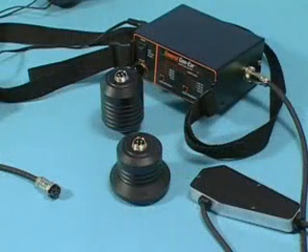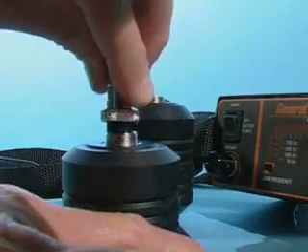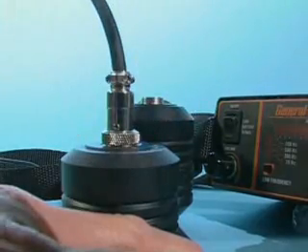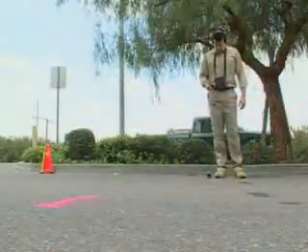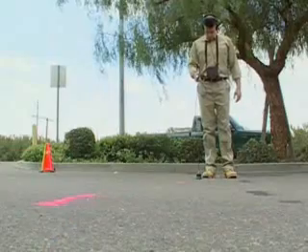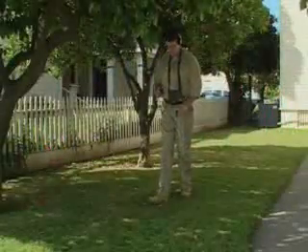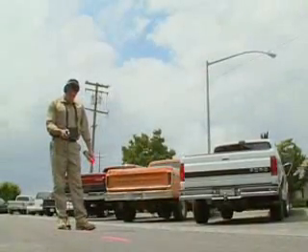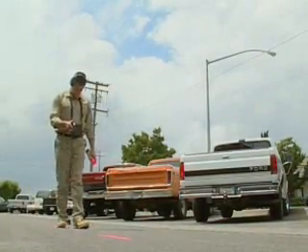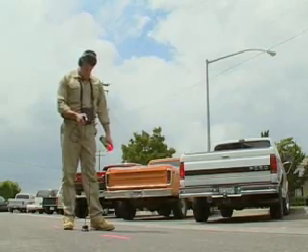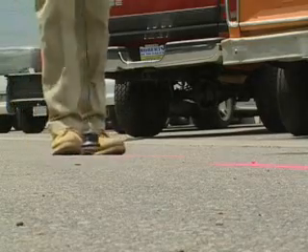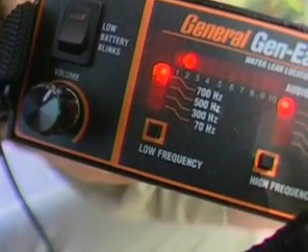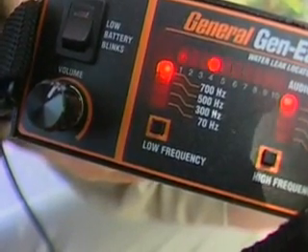To begin water leak location, attach either the ground sensor or the probe sensor, depending upon the surface on which you are locating. Again, the ground sensor is used when locating water leaks through hard surfaces, and the probe sensor is used for leaks under soft surfaces. Then walk the line, taking a reading every 3 or 4 feet. Follow the flow of the water line and note each reading. Do not adjust the volume control. The volume must remain constant in order to make accurate comparisons.